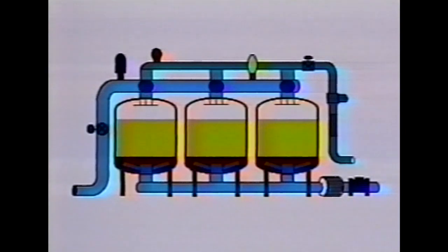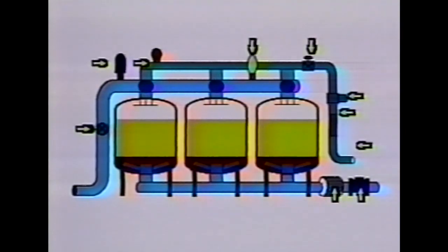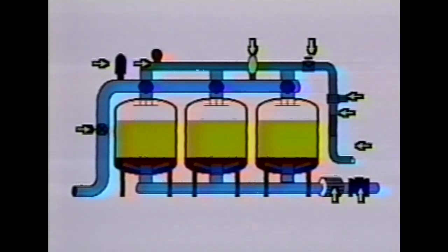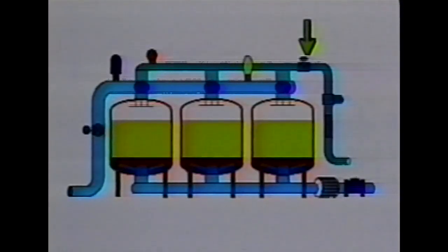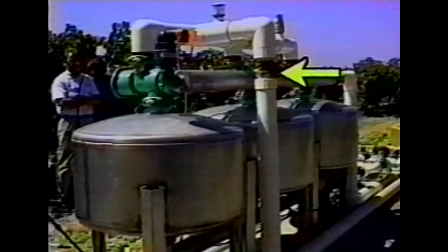This figure illustrates the proper types and locations of various accessories needed for media tanks. There are many essential accessories for the media tanks. These include the backflush flow rate adjustment valve or backflush flow rate restrictor. This valve can be a gate, butterfly, or globe valve located downstream of backflow manifold after the last media tank.